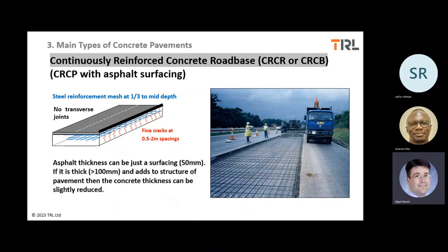And in AASHTO, there is also a provision that if the slab thickness is more than 14 inches, then two layers of reinforcement should be used. In the AASHTO 1993, right, it is suggested like that. Okay. In our experience, just one layer, isn't it?